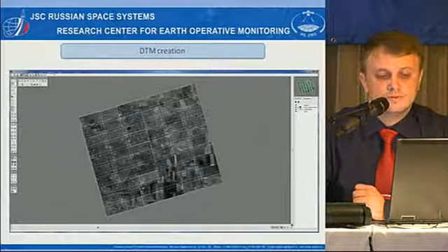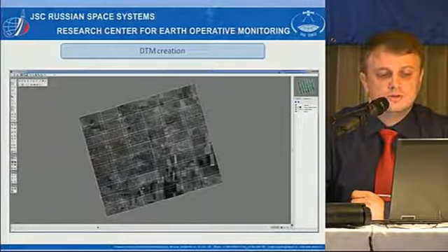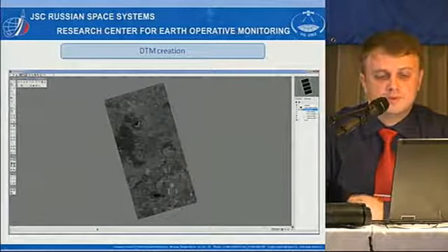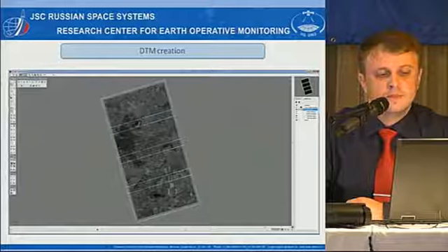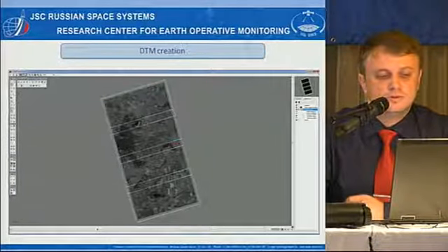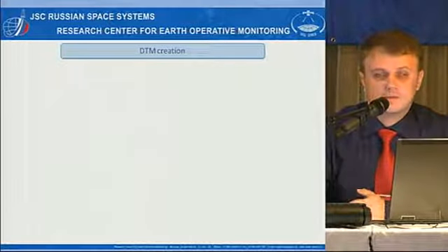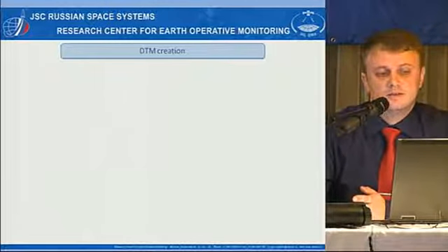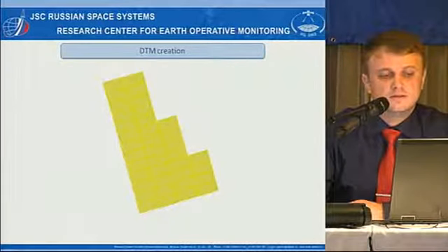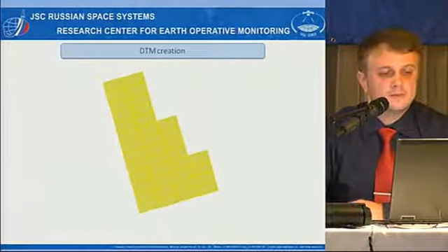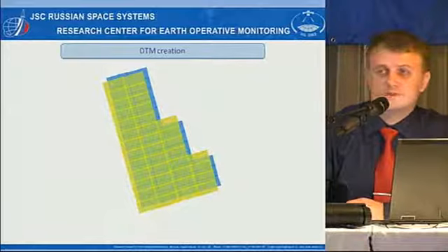As a result of external orientation, we tied all the points from microframes. In overlaps, we measured the ground control points, checkpoints, and the same was done for multispectral frames. We also measured the tie points, both GCPs and control points and checkpoints, and then we didn't use them to build the DTM, but we used them later to build the colored orthophoto. Here you can see the schematic of microframes of the two paths.